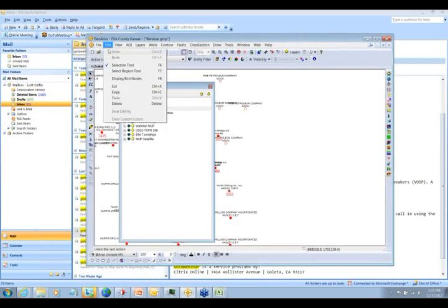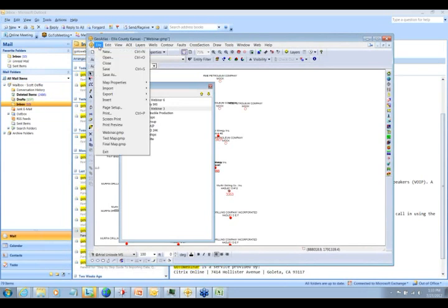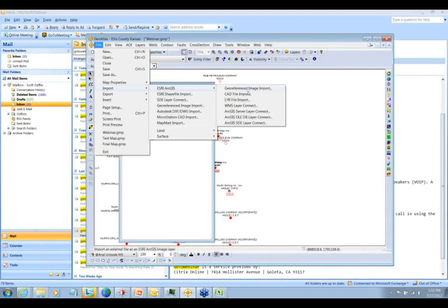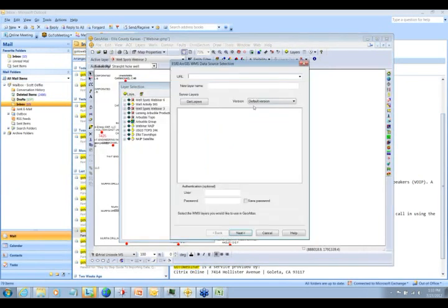You go to File, this is the mapping application, GeoAtlas. You navigate to File, Import, Esri, ArcGIS, and select, if it's a Web Map Service, Web Map Layer Connect. Now you'll notice that there's a place on top, an edit box on top, a combo box, where you can type in the URL. All the URLs that you type in are saved. Those are pretty ugly URLs, but this particular one is from MapMart's cloud subscription service.